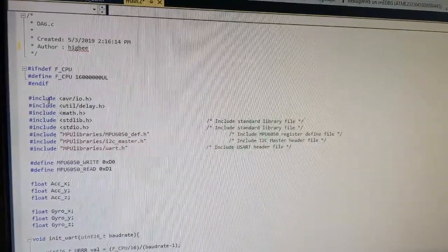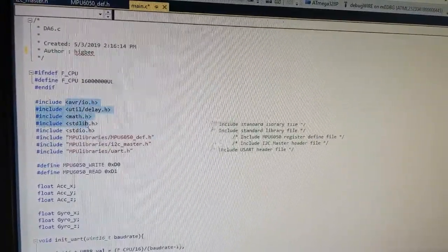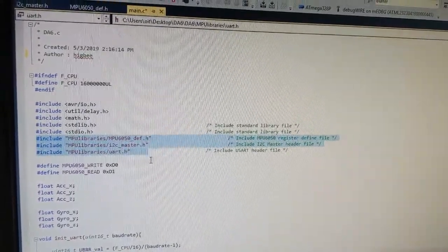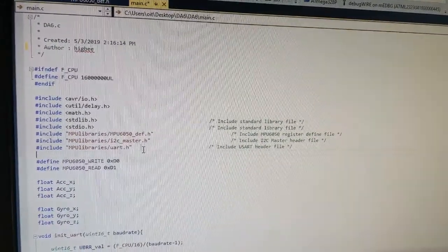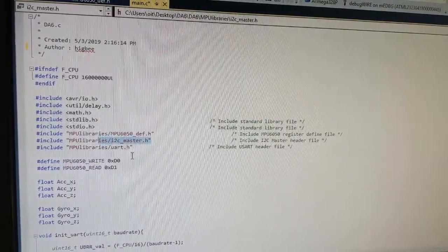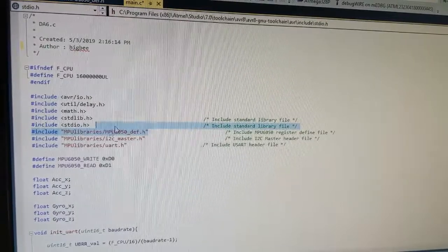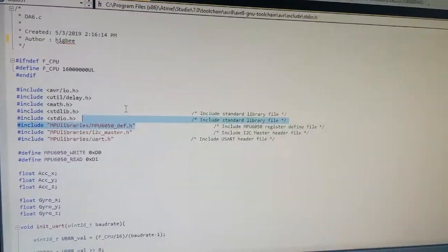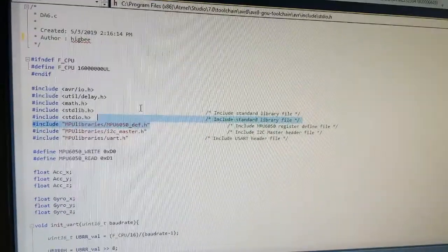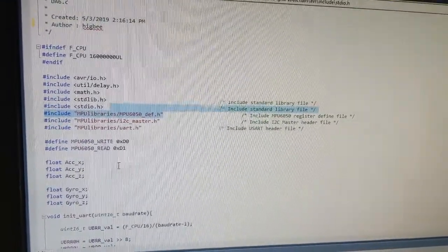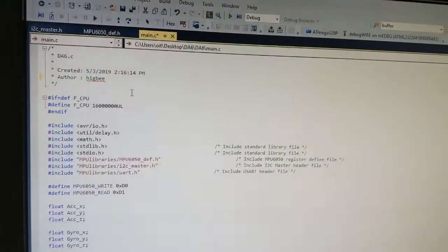So to walk through this real quick, I want to point out some stuff. We use a couple of different libraries. Number one, these are some that were provided by the class to be able to go through and communicate and mainly set up the I2C, and then there's also some I2C related to the specific module, right? The MPU 6050, which is basically an acceleration and gyroscope monitor device. So really the important thing is going to be the few libraries here. Let me point that out.